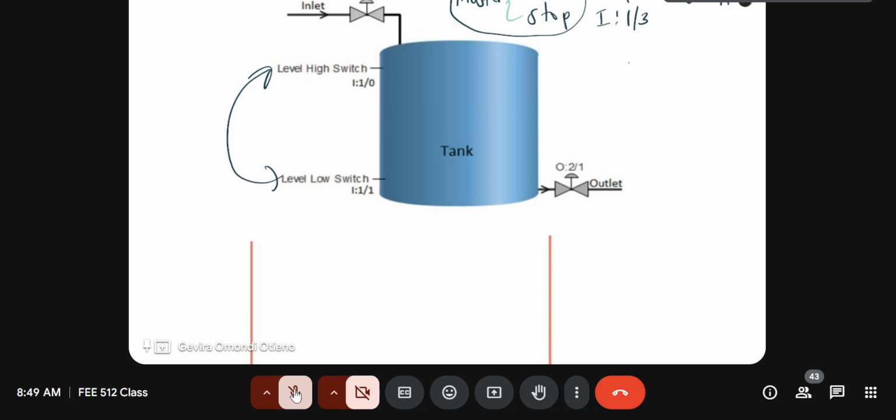Okay, let's start with the basic one. Let us latch our circuit. Usually that's rung 1. That's a rule of thumb. We know the first rung, we need to latch our circuit. And latching our circuit is simple, because a latch is typically your start button. Now, I'm not drawing the physical devices, ladies and gentlemen, because you know the physical devices. So let's say in this case that we are not drawing physical devices. So here now we are PLC programmers.